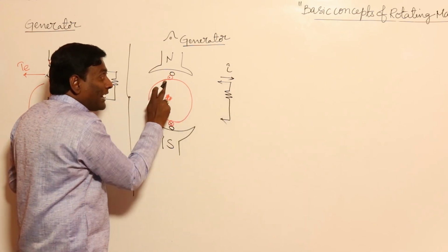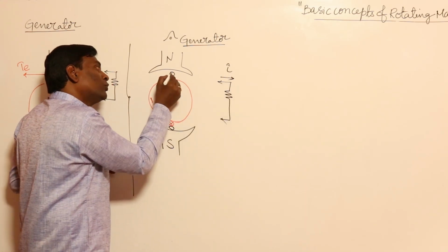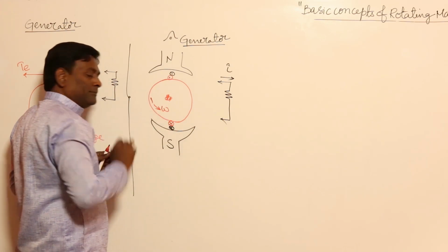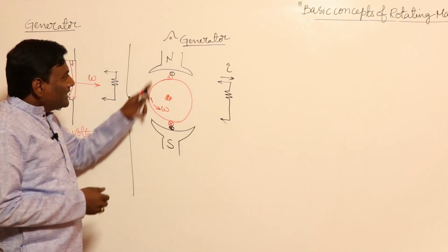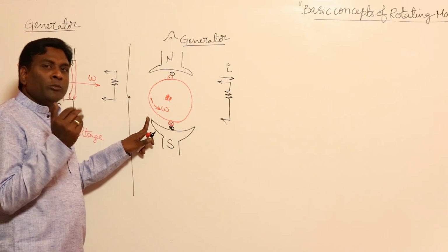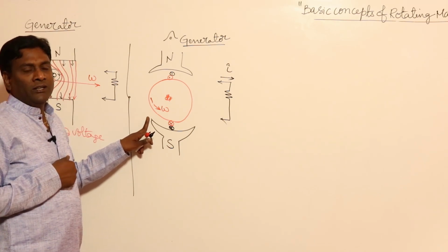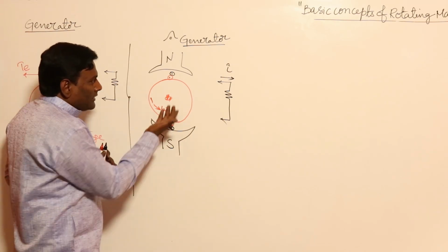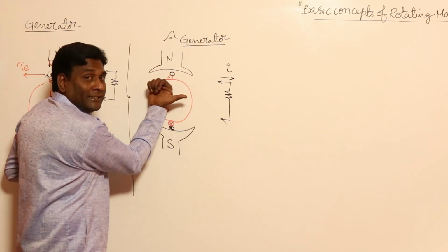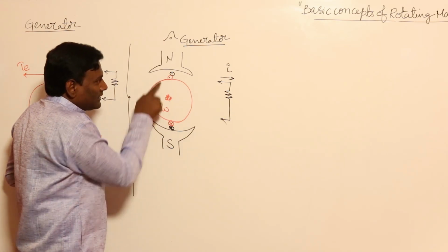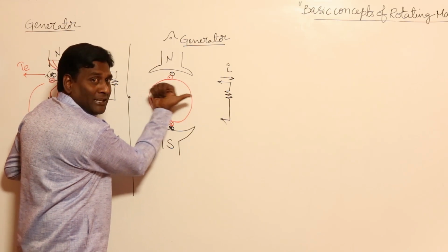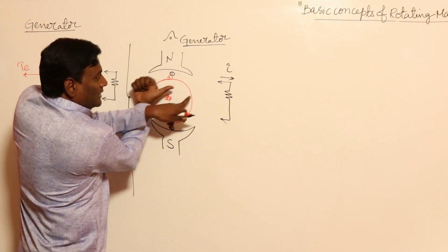Now, for example, once the load is connected, load currents will be aligned with the induced voltage in the generator. So dot here, cross here. The moment currents flow, whenever current is there, automatically flux should come. So cross here, dot here, currents. So automatically my flux will be in this direction. Now flux has to come out here.